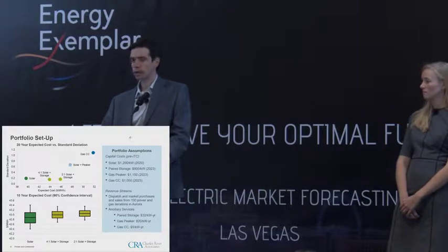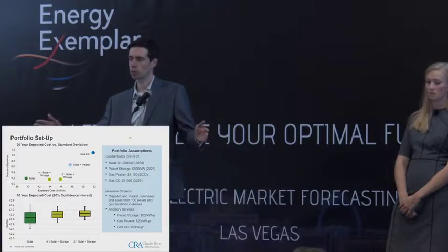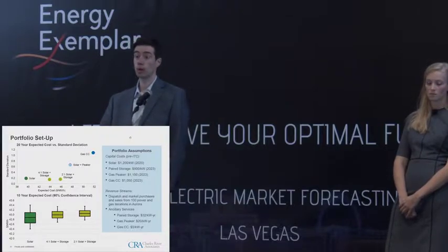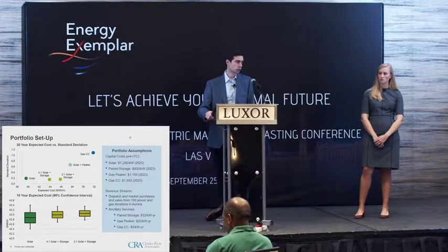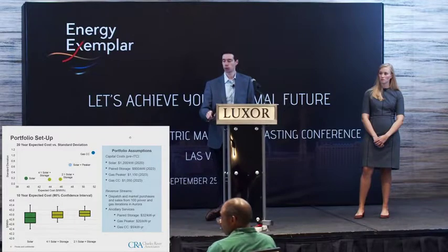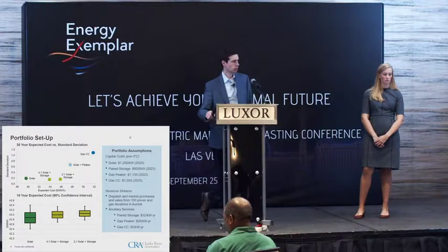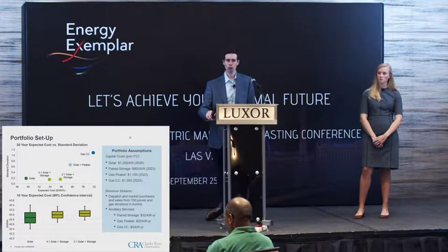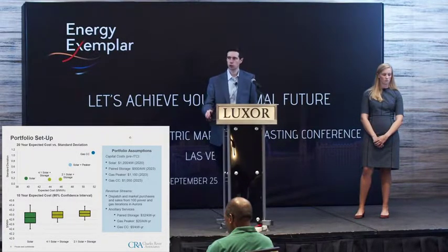We see that the gas combined cycle, just standalone combined cycle in this instance, is higher cost over this 20-year planning period, also has a little bit more risk as a result of dispatch uncertainty, gas price risk that exposes that portfolio option to some uncertainty. And then in the middle, we see some trade-offs between the solar plus peaker option and the solar plus storage option, generally with the storage pairing resources showing a lower cost and a lower risk profile, given the assumptions that we've made here.